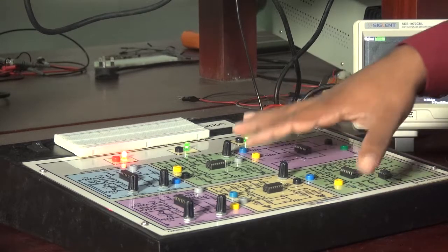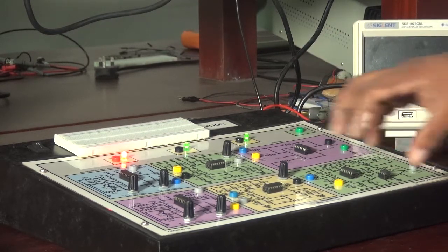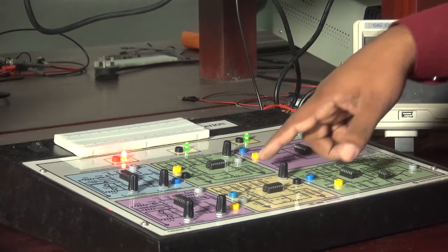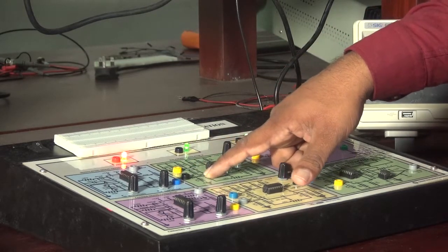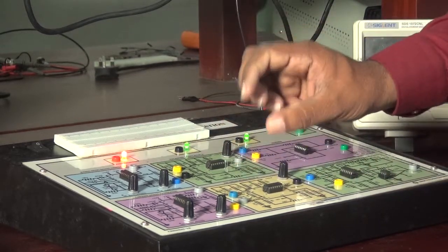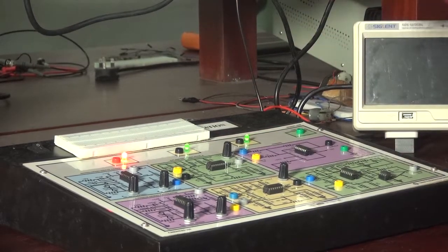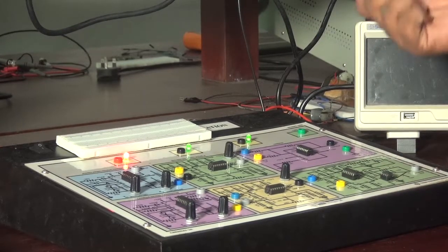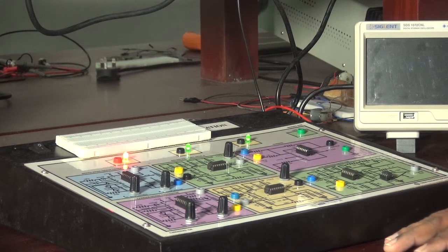Here you can see in the DSB, dual sideband suppressed carrier modulator, there should be two amplitude modulators. To one we are giving the direct carrier signal, and to the other modulator we are giving the 90 degree phase shifted carrier signal. Then we get the outputs of the two modulators and send them through a summer. That means we add the modulated signals together and we get the DSB output. We have learned this in the classroom, so we will see the waveform and the spectrum.